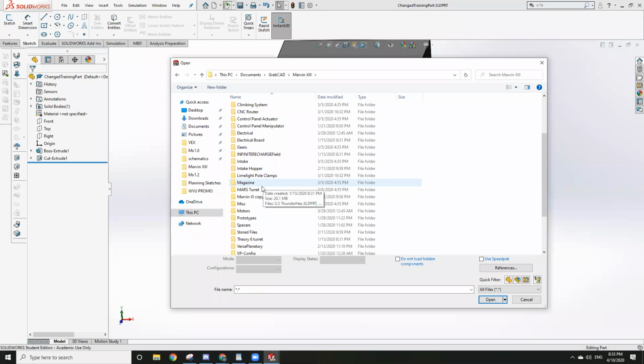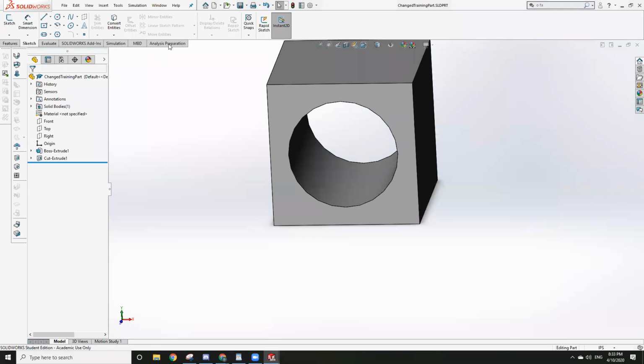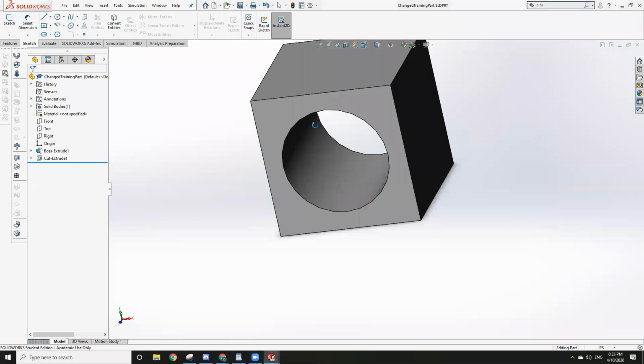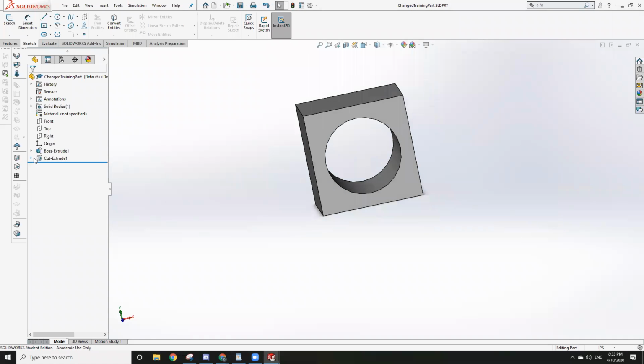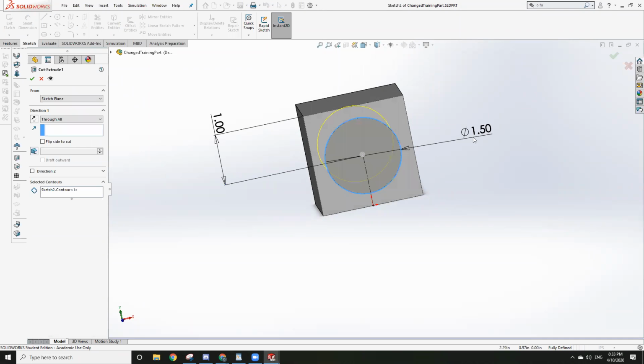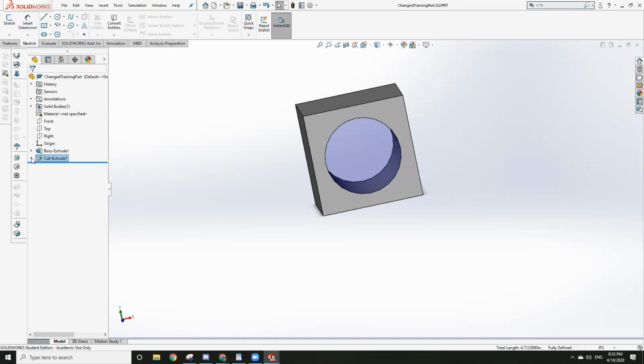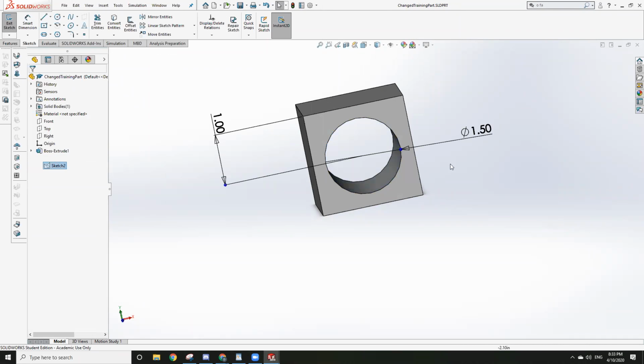I suppose you guys probably can't open one of those parts either, so we're going to make one of those parts. We'll look at this right here and edit this feature. Actually, no, wait, it's not the feature, it's the sketch. Sorry. All right, we're going to make this 1.125.